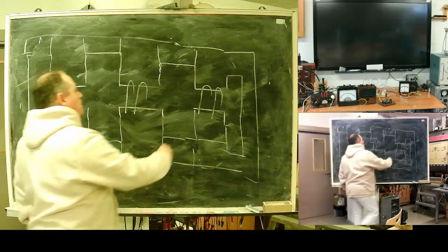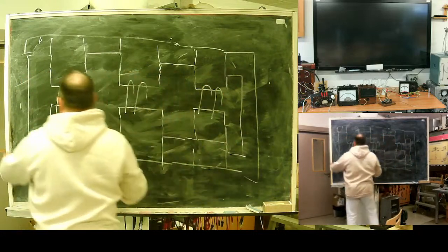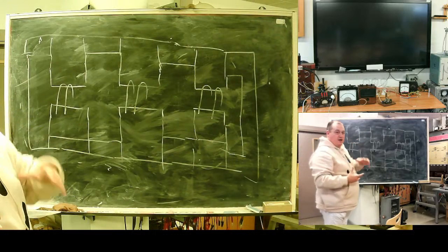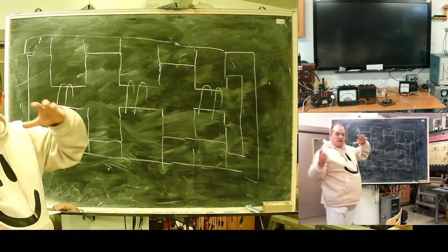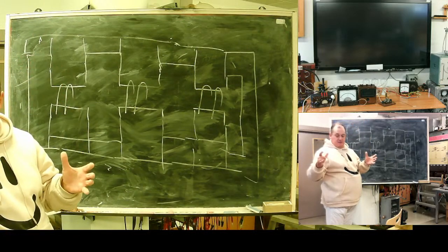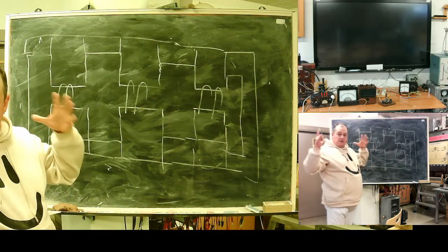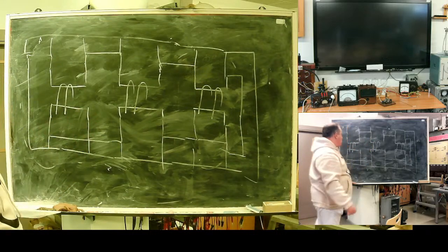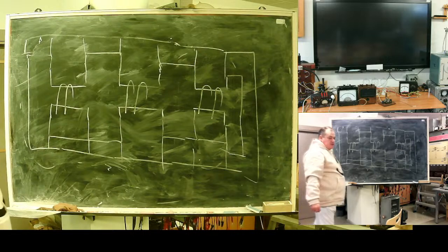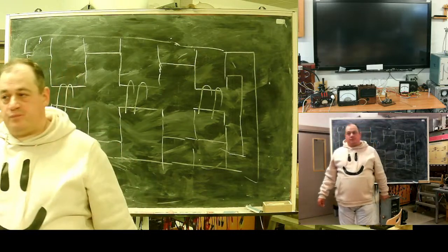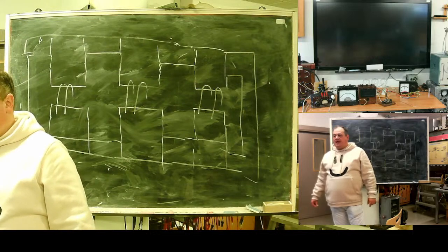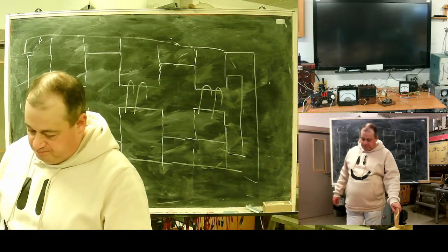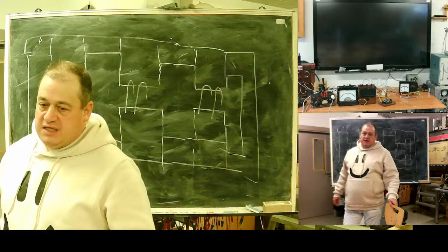Each winding block sits in its own separate section, but all this is like one piece of steel, usually assembled vertically. Such kind of transformers, screened or armored transformers, people say they were firstly designed for submarines to reduce the magnetic field of the submarine.